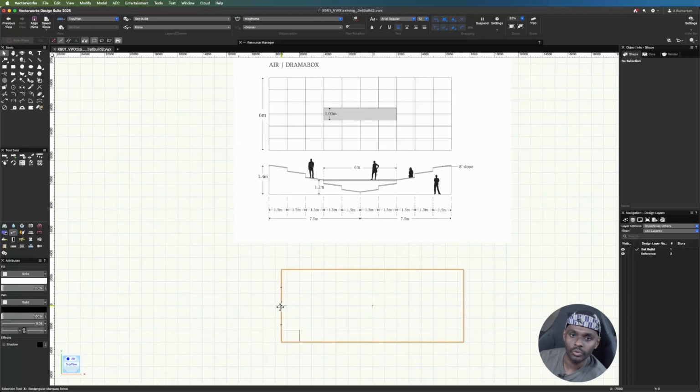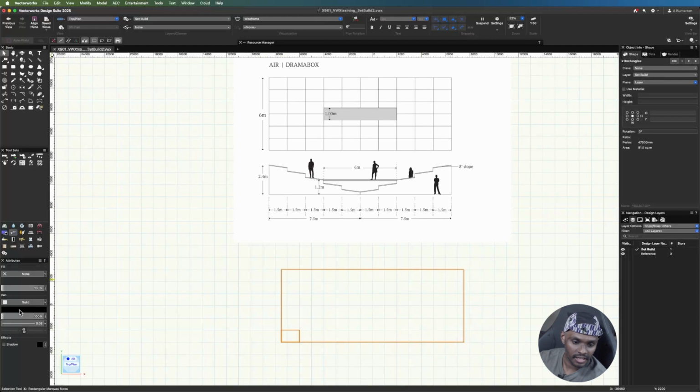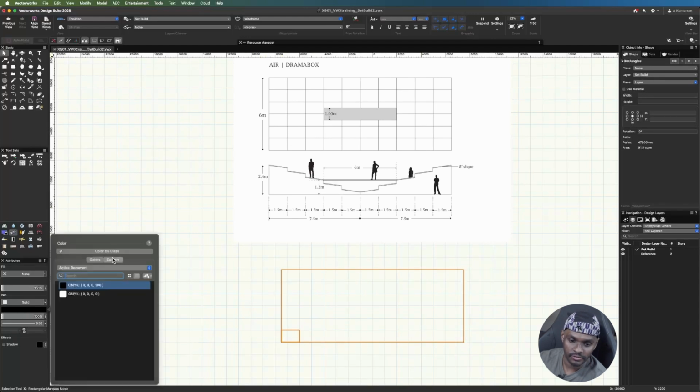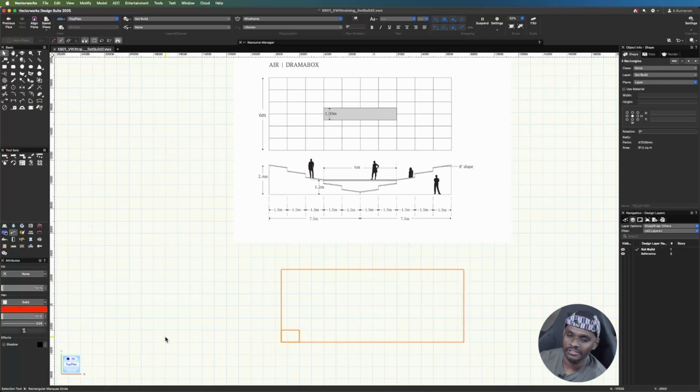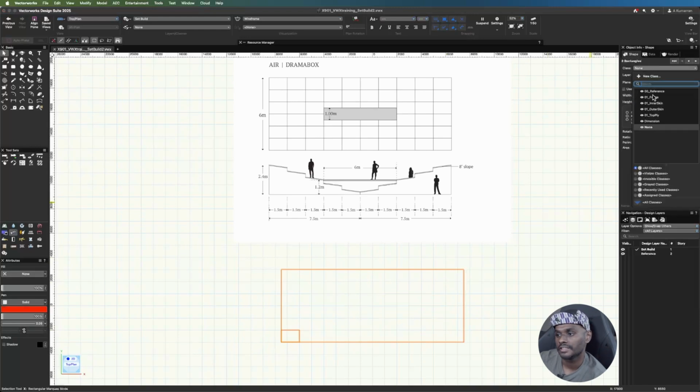So what I'm going to be working with is this little rectangle over here, and then from there we'll just multiply it to assemble the larger drawing as a whole. Just to be clear that this is where I'm going to be working, I want to select all of this, and I'm going to change the pen color to a red color, kind of like boundary lines, just so that I know that's what I'm working with. I also want to make sure that they are all in the set build layer and their class is reference.